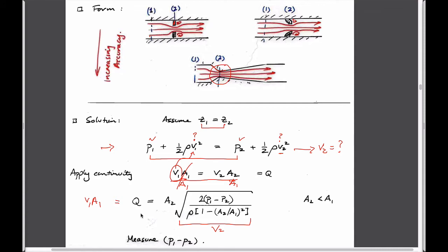And you'll note, of course, that you don't need to know absolute pressure. All you need to know is the differences in pressures between these two things. And so a high accuracy differential pressure transducer can be used. The great thing, from a practical standpoint, about a differential pressure transducer is that it doesn't matter if the pressure is 1 kPa or 100 kPa or 10 million kPa.